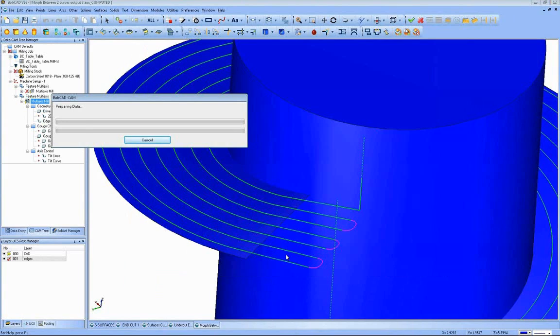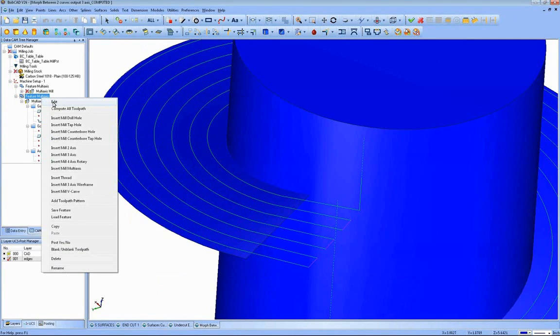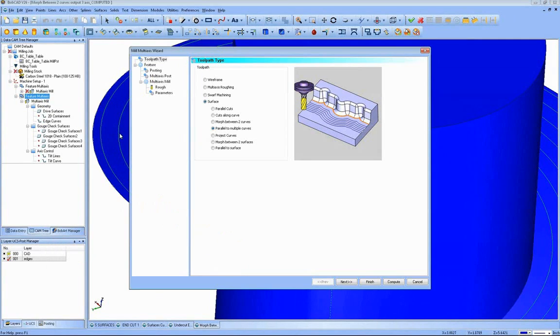And we'll give this just a moment. So you can see a direct is just like it says, direct connection. That's the one thing about these toolpaths that you want to understand, and even with any of the 3-axis and 2-axis toolpaths nowadays, is once you generate it, take a look at your toolpath on the screen. If it's not what you want, go back into it, make an adjustment, recalculate it. Look at the toolpath generated on the part, look at the simulation, start tweaking it in. It's a lot easier to get the basic toolpath calculated first and then tweak it in from there than to just try and go right to the finished product the first time and guess on half your settings probably as you go through it.